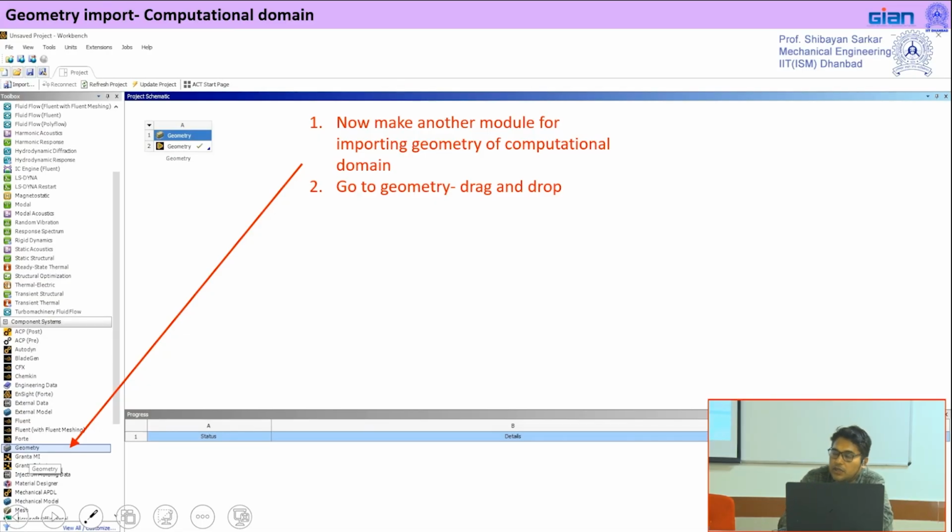So this part of the geometry we have recognized, we have performed the Boolean operation. There were two bodies, two parts, and we combined them through the Boolean option, we made it subtract, then we defined its material characteristics as fluid, then we generated it, and now it is ready. It is now inside this particular part. This particular portion, that means geometry A, contains the rotating body.